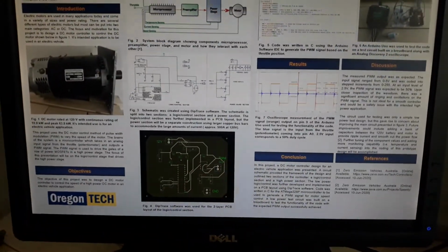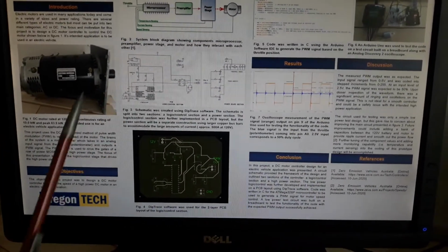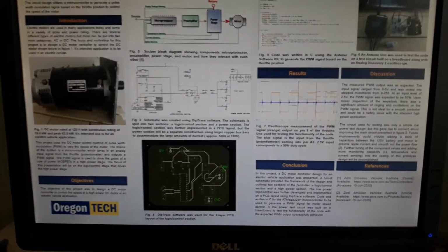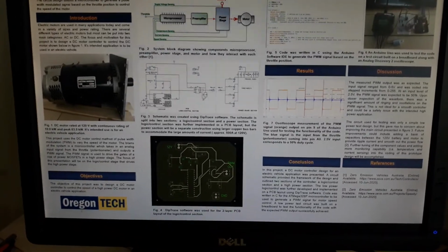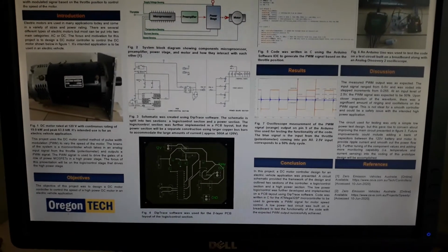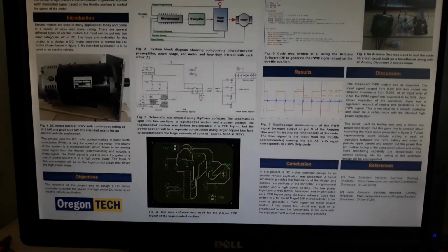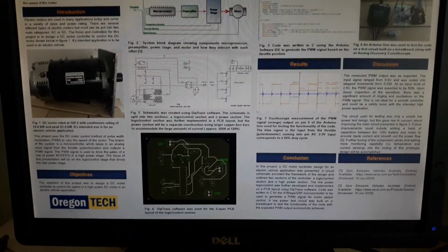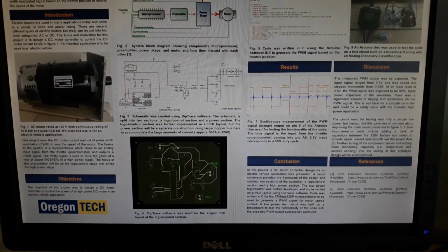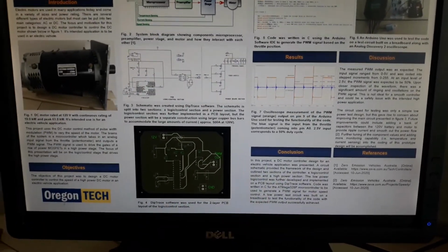Also, the reason why I chose the Atmega 328P is that I can take advantage of more capabilities, like temperature sensing and current sensing. I can monitor the speed of the motor, and I can monitor the voltage of the supply as well, and make decisions based on that feedback. That's something I can do in future improvements to this prototype design.